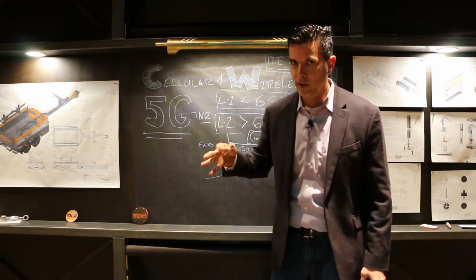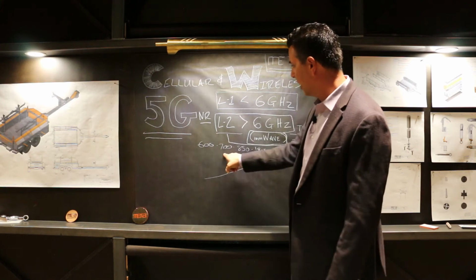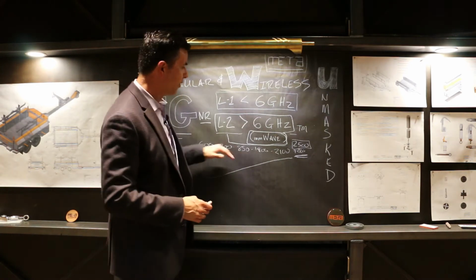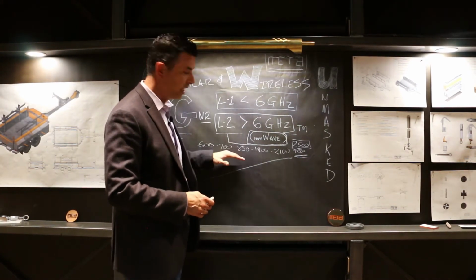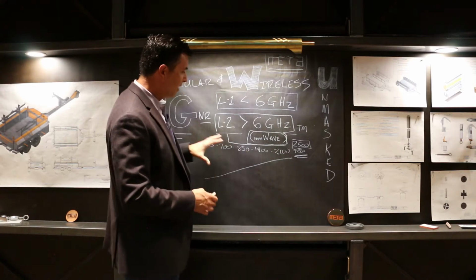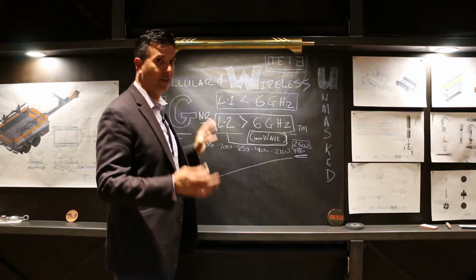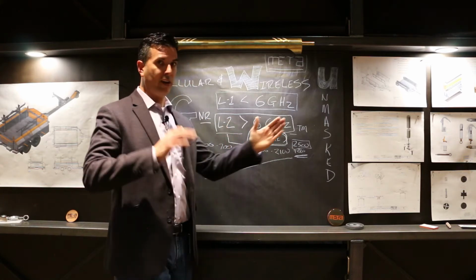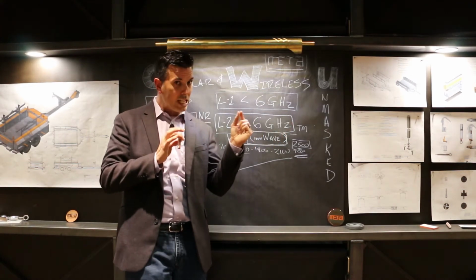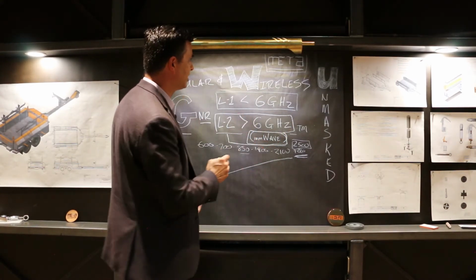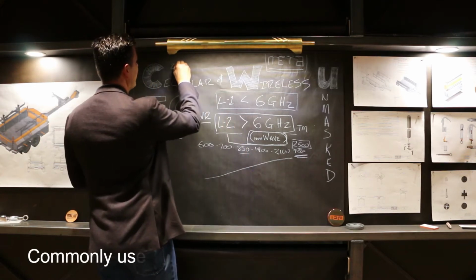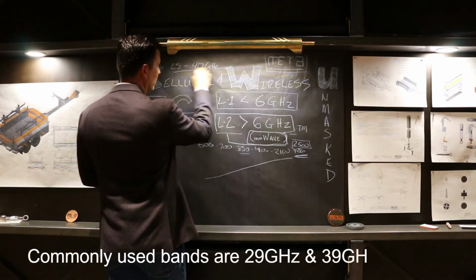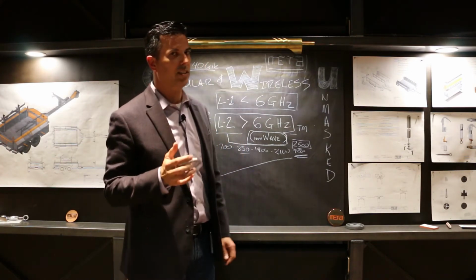What does millimeter wave mean? If you look at the wavelengths of different frequencies throughout the cellular band, the wavelength for the lower frequency stuff, which is your long range, your long reach cellular bands, these wavelengths can be quite big, a couple of feet. At 850, it's about 1 foot per wavelength. Millimeter wave means you're going from this kind of a wavelength to really, really tiny stuff. And the millimeter wave stuff is your frequencies in the 25 to 40 gigahertz. I mean, we're talking really high frequency stuff.